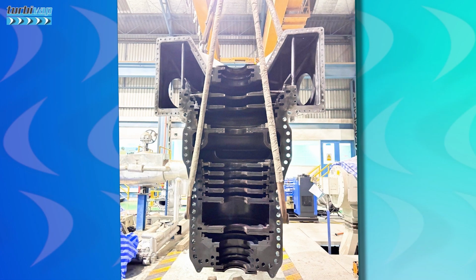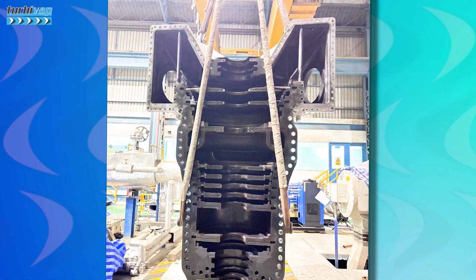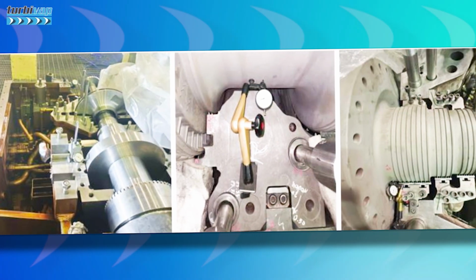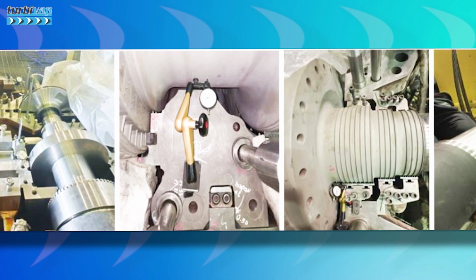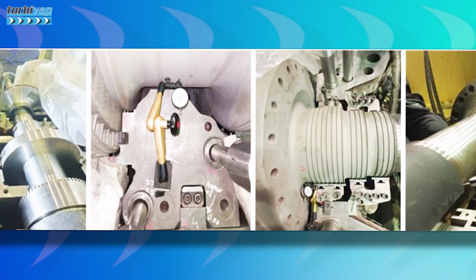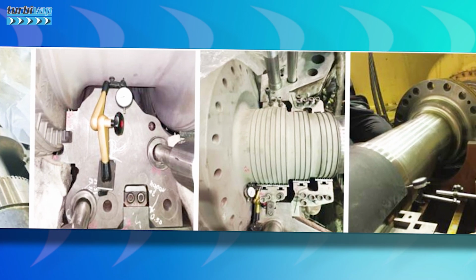Each rotor vane and diaphragm must be inspected for erosion, cracking or deposits using non-destructive testing as a tool. Also penetrating liquid, magnetic particle, ultrasound. The rotor is the most critical component. It undergoes a thorough warping check and non-destructive tests, also of high sensitivity, especially in the areas of stress concentration. In the bearing journals, the casing is also cleaned and measured to check distortions, warping, alignments, flatness, joint plane, in short, a multitude of criteria, repairs, modernizations.